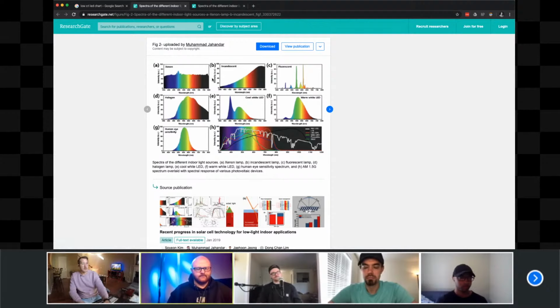What it comes down to is that different light sources can render colors better than others. Things like incandescent lamps are going to be higher CRI, and CRI is from 0 to 100. A lot of times we'll look at a fixture and see a CRI of like 95, and that's going to mean it will render really good color, especially for camera.